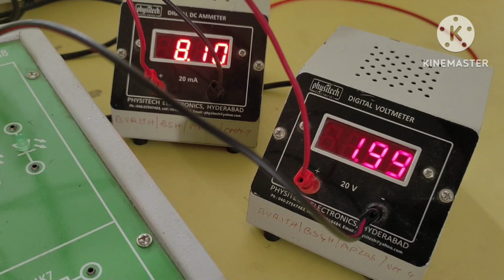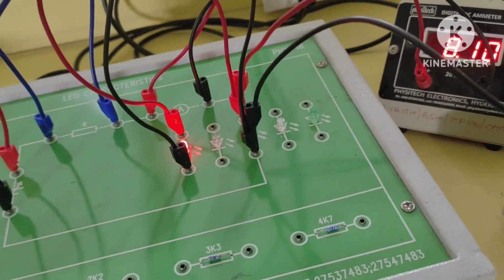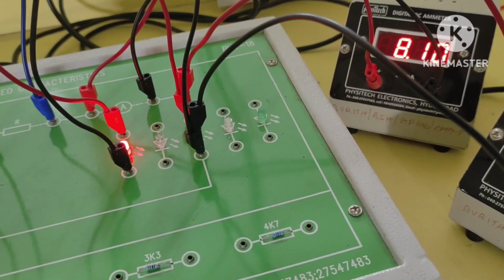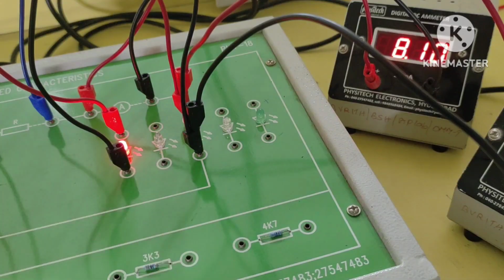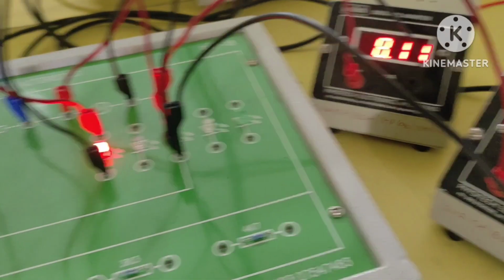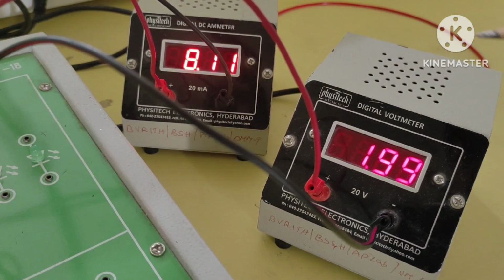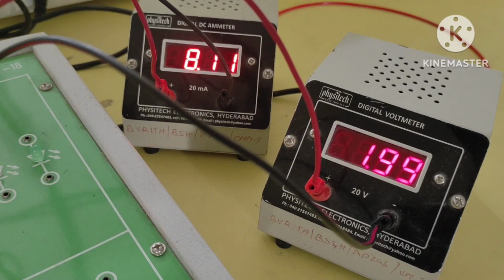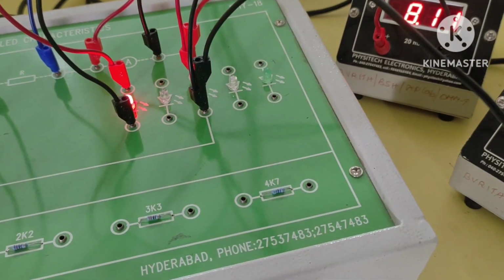This voltage is the voltage drop across the LED, because from the parallel components point of view, it's split. The resistor and the LED are both in series. Some voltage drops at the resistor, some voltage drops at the LED. Now we are measuring the LED voltage by giving parallel connections to the LED. This data is related to the IV characteristics of the red LED.